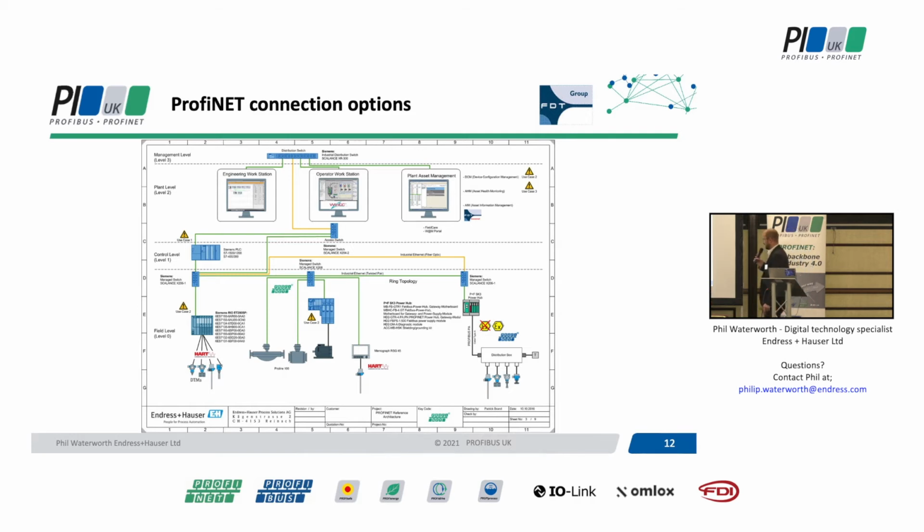And we can see here we've got various PROFINET IO and what else have we got here? We've got some sort of PROFINET proxy to Profibus PA there. So again, things like the proxy and the remote IO will have communication DTMs by the manufacturer. Put that into the FDT tool.